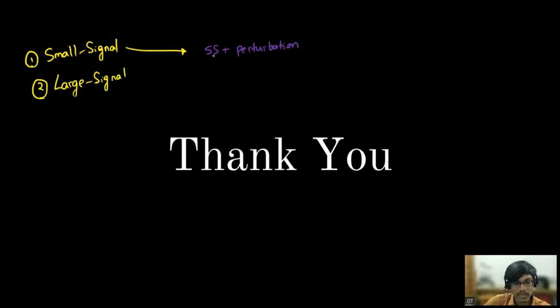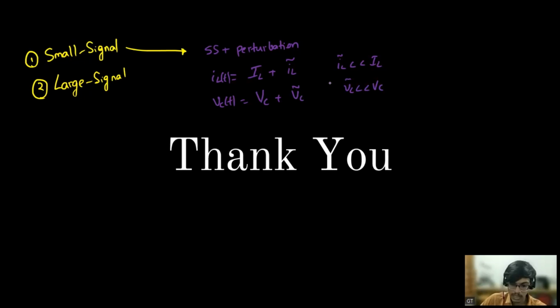If I consider IL, it will be IL steady state plus IL perturbation, say this is IL of t. Similarly, VC of t will be VC steady state plus VC perturbation. It relies on the fact that IL perturbation is much less than IL and VC perturbation is much less than VC. So we consider some small perturbation around that steady state and we get that small signal model.